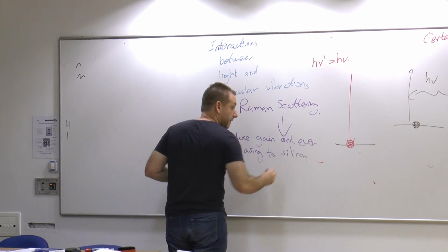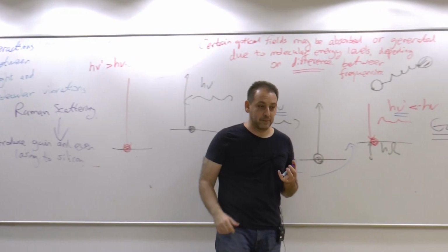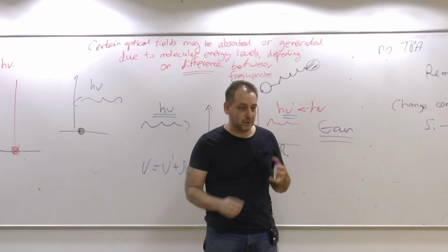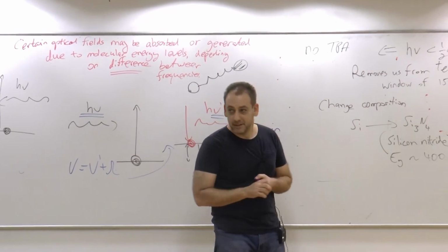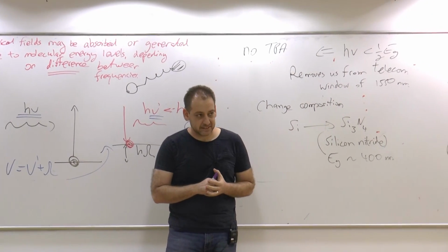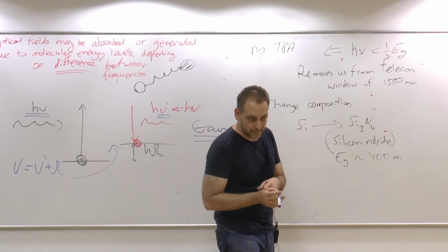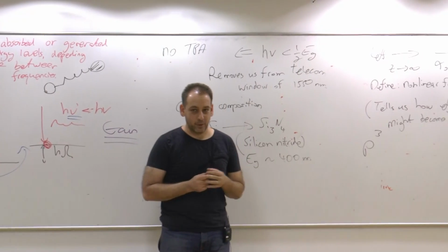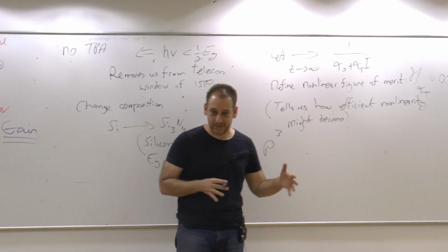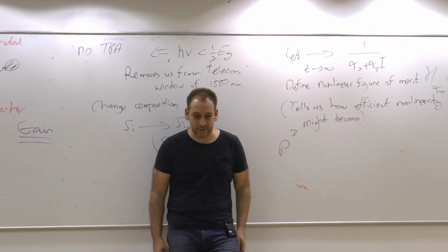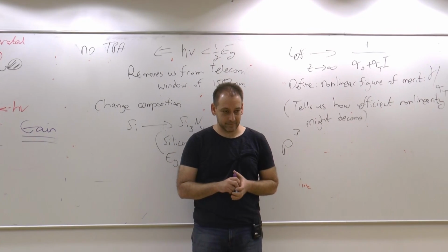to silicon. And we all like to say there is no silicon laser, but we have to be a little bit more careful. There is no silicon laser in the semiconductor sense of the term, because already in 2006, we had reports of a silicon Raman laser, which are very beautiful. This is a very heroic experiment. It has many complications that I will require next week to explain the entire scale of. I will get to it, but nevertheless, it is a silicon laser.